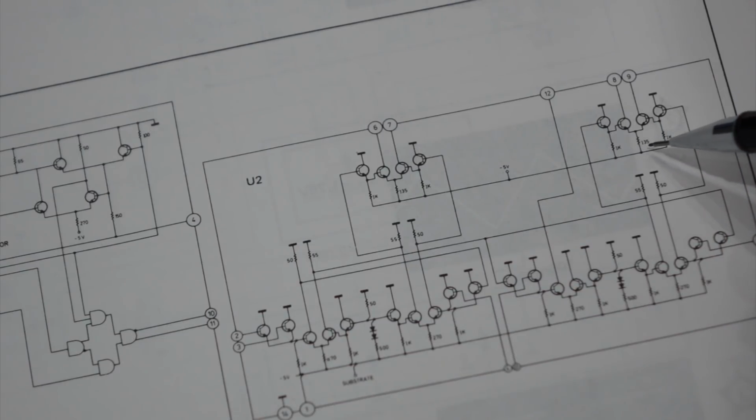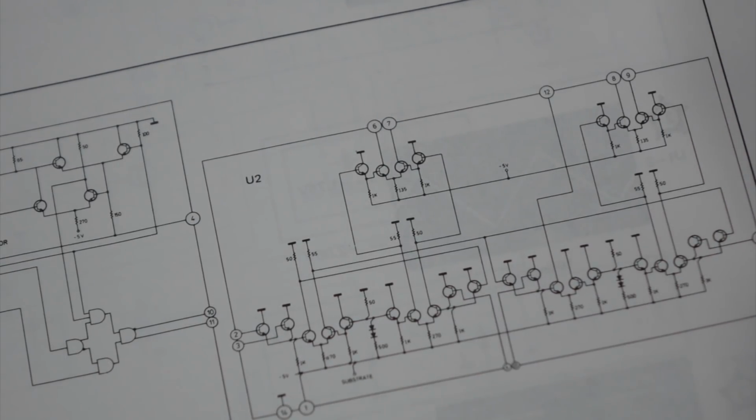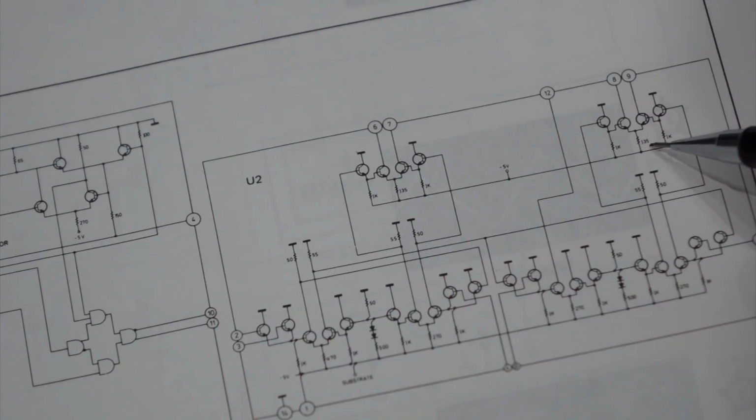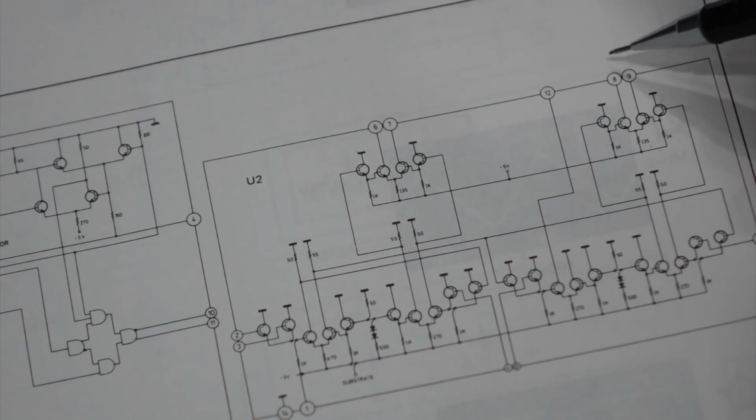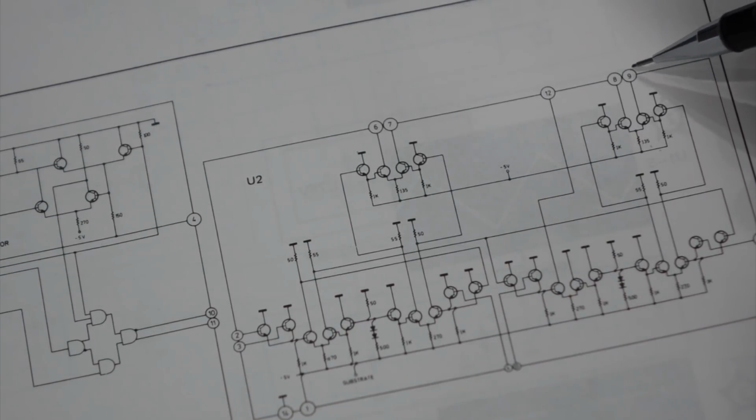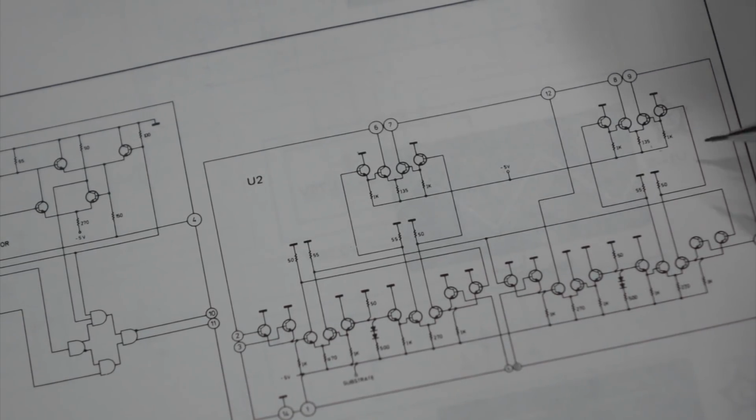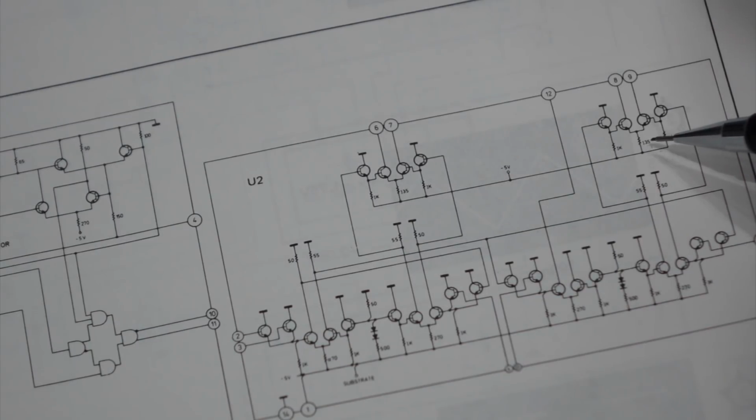They have 100 and what is it? It's minuscule. 135 ohms, so about half of what this is, to do the double voltage, and there is no 50 ohms inside the circuit. Actually, it's outside. On the PCB, there's a 50 ohm resistor. The output stage has double the swing.